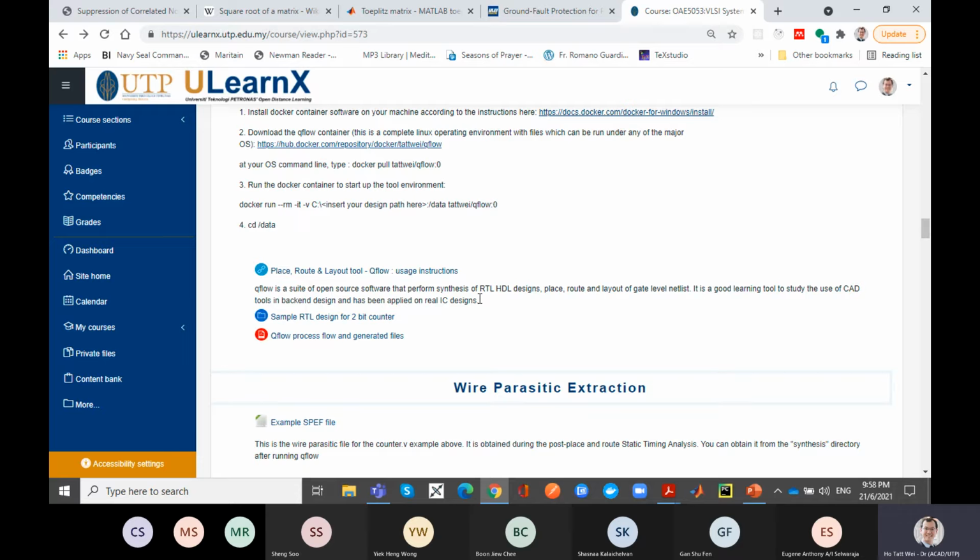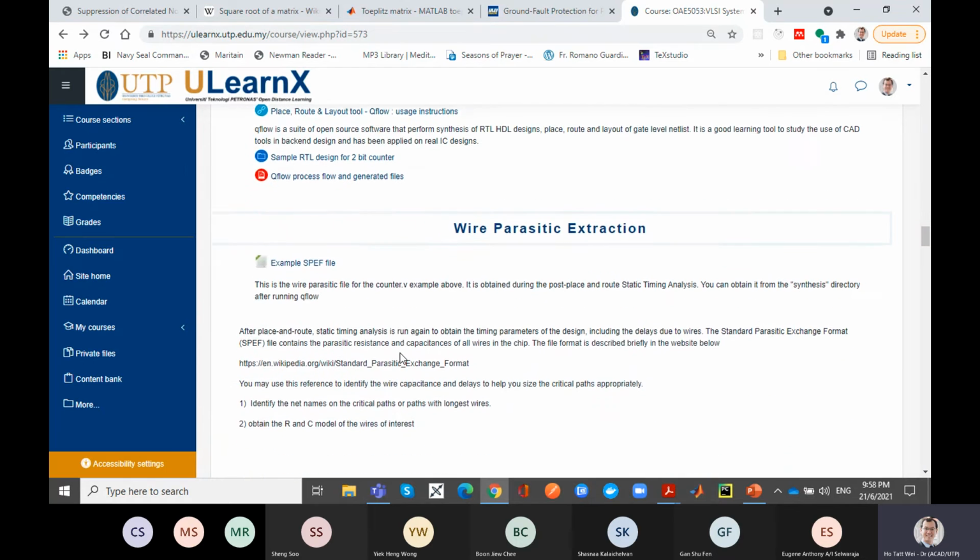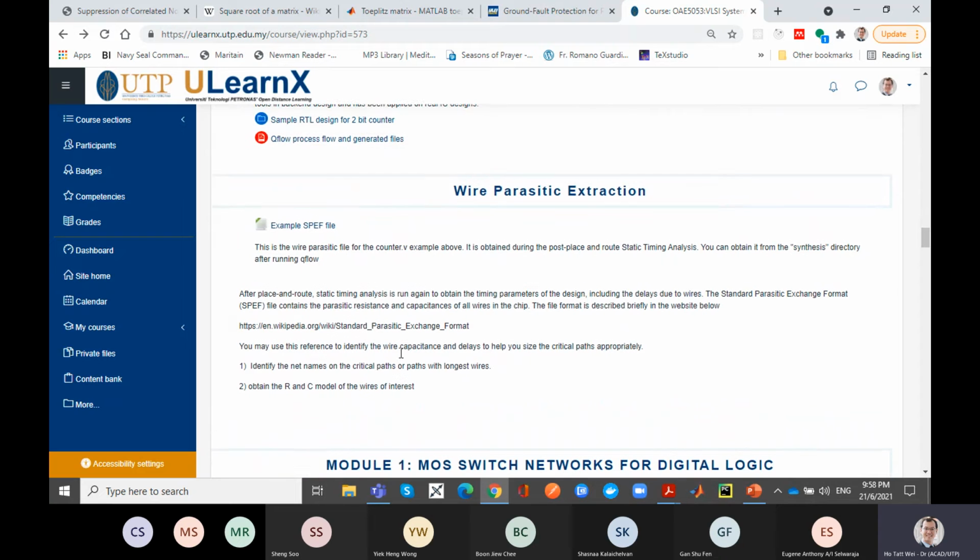Right? I'm not going to make you do that because our goal is not to make an IC. It's to get you through the process. So I would just say you can ignore the DRC check, as long as you have your pre-static timing analysis, your post-static timing analysis, and your spec file, you have enough already. Because I just want you to do the analysis. The whole point of this is that you get some realism. It's not just that I give you any kind of circuit, the circuit has actually been synthesized. So you can see that this can be applied in any design in the future in your workplace. So don't worry about layout issues.